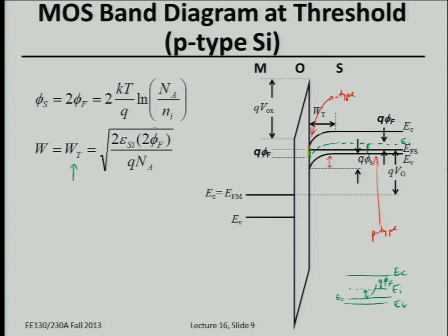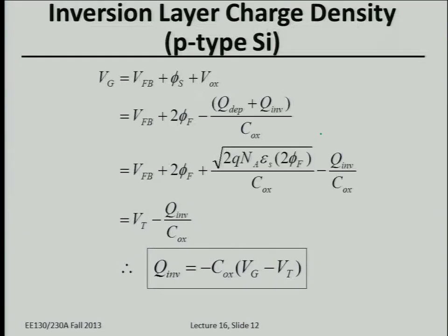If you're linearly increasing the gate voltage, Q has to increase linearly with the gate voltage, but you don't really have to move the bands too much to get that linear increase in electron concentration at the surface. So the energy bands don't really move much once you form a strong n-type layer at the surface. It has nothing to do with shielding, it's more basic than shielding. And it's pretty simple math.